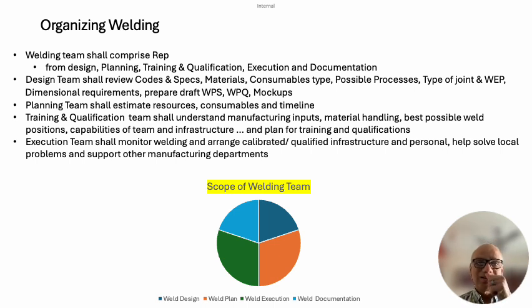When the design office is doing a detailed engineering of our part or equipment or sub-assembly or assembly, then at that stage, depending upon the accessibility, depending upon the requirements of the properties, ease of welding, ease of fabrication, ease of handling, the number of subsystems in which we will be executing the fabrication and then doing the final welding to have a full subassembly or equipment, all those discussions are done, and the codes and standards are referred to and understood.